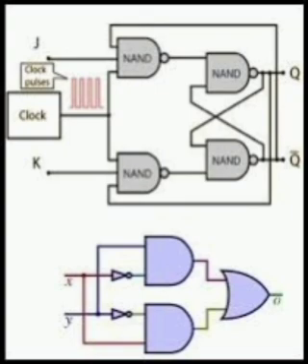Given mux 4 is to 1 to be implemented mux 16 is to 1, required number of mux 4 plus 1 equal to 5. Given mux 4 is to 1 to be implemented mux 64 is to 1, required number of mux equal 16 plus 4 plus 1 equal 21. Given mux 8 is to 1 to be implemented mux 64 is to 1, required number of mux equal to 8 plus 1 equal to 9.